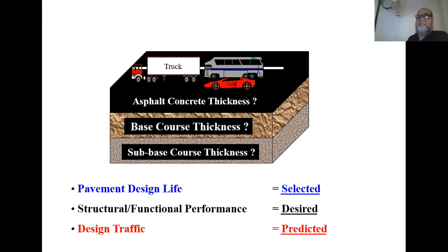We only design for vehicles with at least 6 wheels. The question is why? There is a simple answer: because the cumulative load of those vehicles does not matter much. So instead of wasting your time, you don't consider them in the design. Even if you consider them, it is not going to impact your design much.